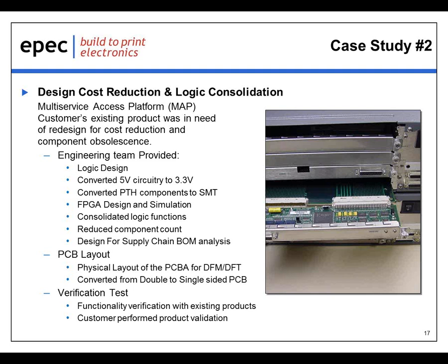We also refreshed the technology. They used 5-volt logic, so we converted from the old pin-through-hole technology into updated 3.3-volt logic and condensed parts into the FPGA. You can see the new Xilinx FPGA in the center of the board.